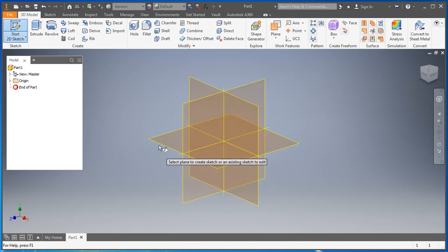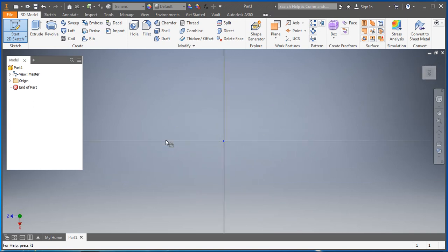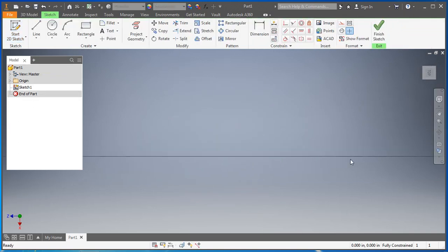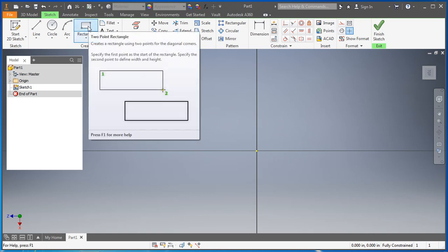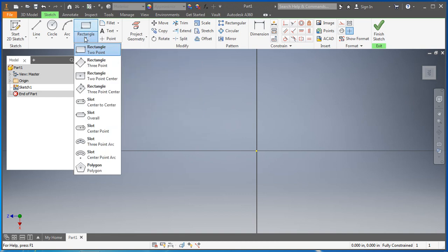So making the 2D sketch, we can start on any of the sort of cardinal direction planes here. This is the flat plane. This is the one we want to start with, called the XZ plane, or XZ if you're Canadian. Click on that one, and then what shows up is a set of crosshairs to make our first 2D sketch on. So what I'm going to start with is a rectangle, because we're going to make the base of the box for this water piano project.